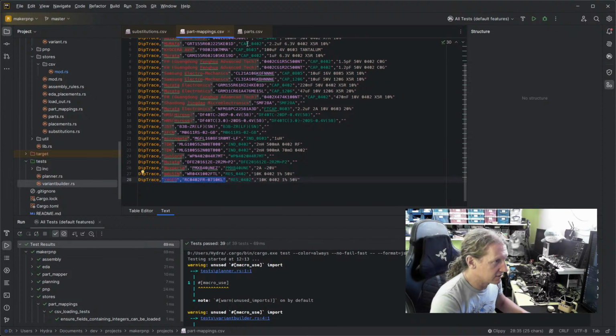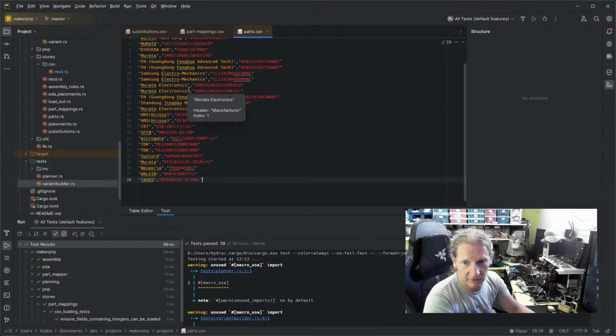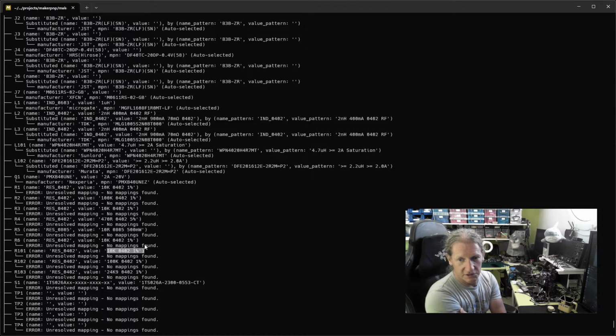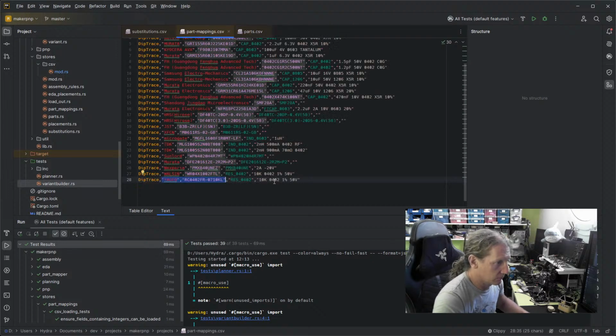We could pick either of these two resistors right now. So in order to choose which one, we need to look at the other ones and see if any of them say a high voltage rating already. So no voltage rating 10k, no voltage rating, no voltage rating. So we're free to pick whatever. I know the design is for low voltage sources. So let's look at this. They're both 50 volts, they're both 1%, so fine.